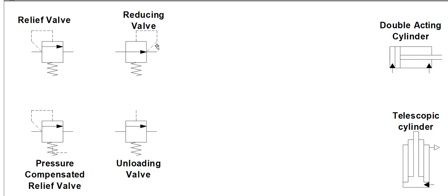If we go over here, we can see our pressure reducing valve. The pressure reducing valve is normally open, so oil comes in here and flows straight through. But it has a pilot line on the outlet of the valve, pushing against a spring. If this spring is set at 1000 psi, oil can freely flow through, but once the outlet pressure of this valve reaches 1000 psi, the oil pressure comes around and pushes this arrow away from the center, which starts to restrict the flow through the valve, creating an orifice, which creates a pressure drop.